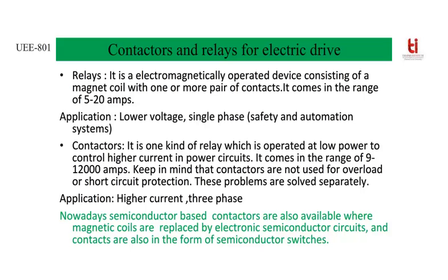Now from this discussion it is clear that relays and contactors provide a path to the current. The same thing is possible with the help of power electronic switches. We have discussed that for high power applications, thyristors are there. When the thyristors are triggered, or firing pulses are given, the thyristor will be on and it will allow current across the circuit. For AC motors, we can use bidirectional switches as these relays and contactors. For DC motors, unidirectional switches will be used. Bidirectional switches can also be developed using unidirectional switches. So nowadays these relays and contactors are being replaced by power electronic switches.